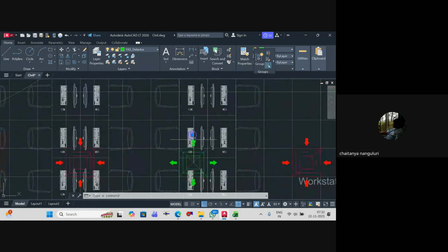Why? Because it is near 1 meter. It should be lesser than 1 meter from your supply duct. But now, don't you think it is lesser than 1 meter from your supply duct? Can I have it like this? At minimum, one meter of distance between the supply air diffuser or supply air grill and the detector should be there.